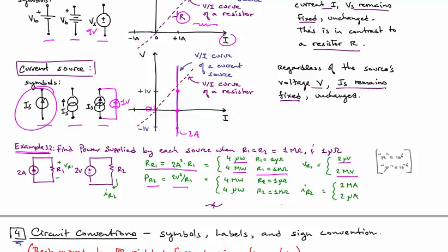It's the opposite for the voltage source. Look here, if R2 is 1 microohm, and we do 2 squared over R, 2 squared over 1 microohm, we end up getting 4 megawatts. So a 1 microohm resistor in R2 there will actually absorb 4 million watts. And that's because the current that is going to be flowing in that case will be 2 volts divided by 1 microohm, or 2 million amps. So that results in the high power.